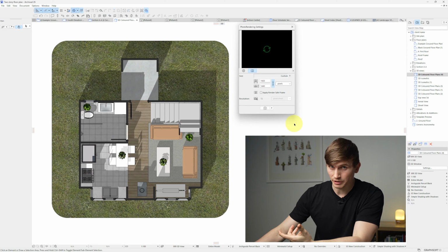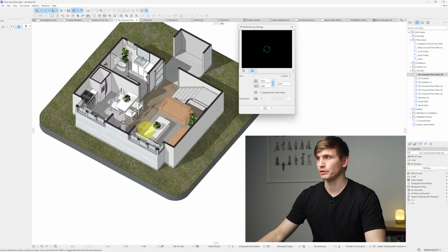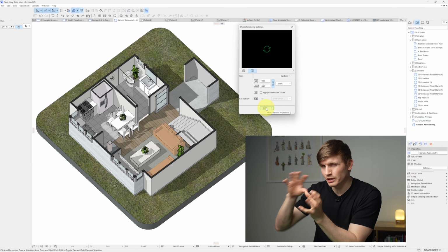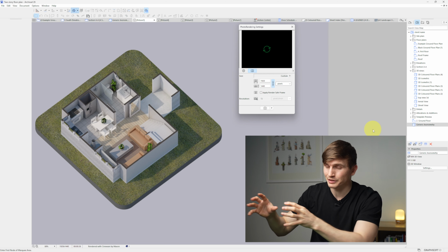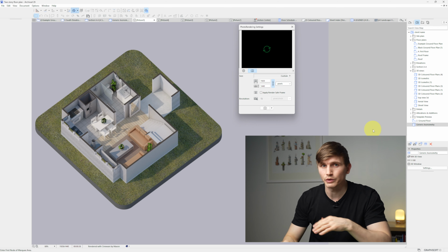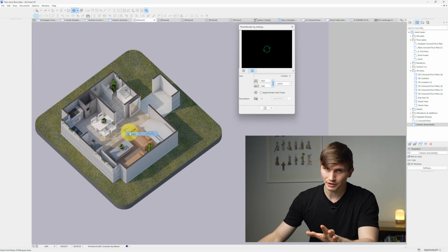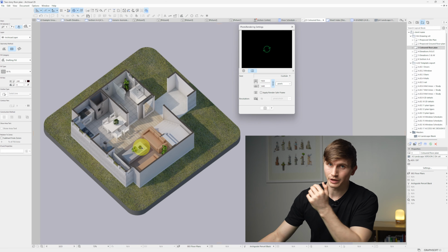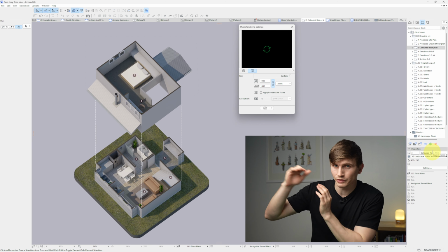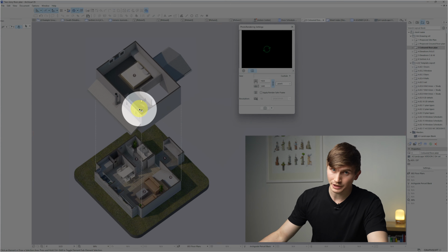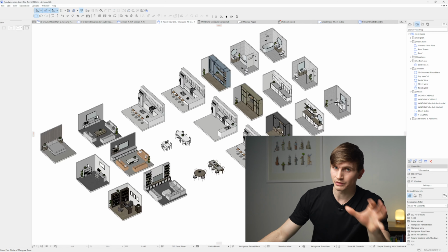Because this is all modeled up in 3D, if we just pivot down and across with the same settings, but a slightly different view, we can now hit render again, and we can create an isometric that's so easy to read, even if you don't know how to read plans. Again, we can copy that, bring it onto our layout, then also add extra annotation, just for that extra clarity and presentation. With this process, we can even create a second story with a bedroom as well as a study, using the preset rooms that have already been set up in the template.